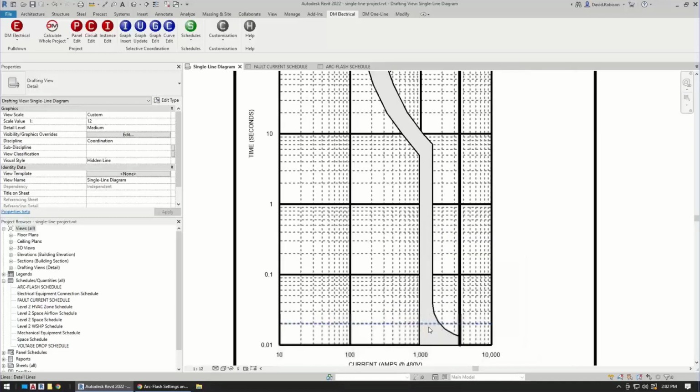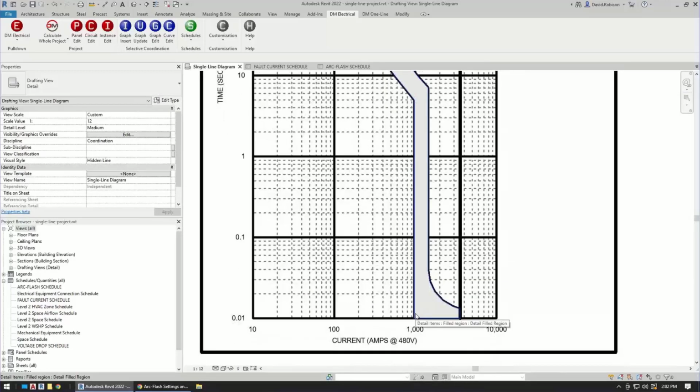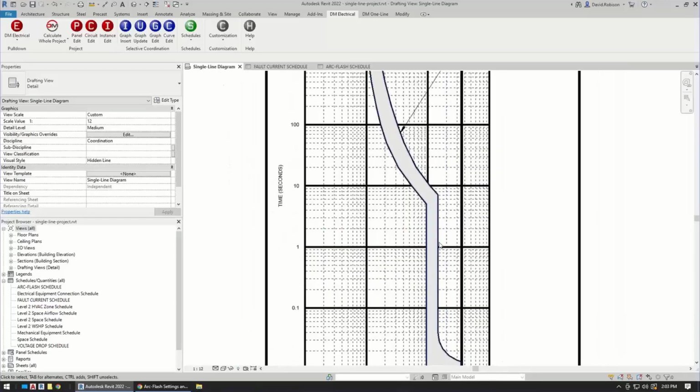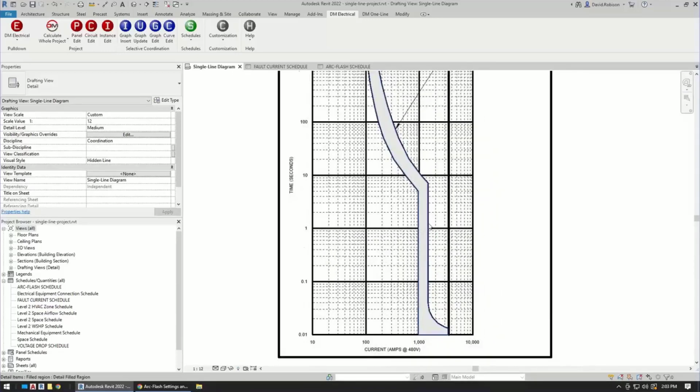So scrolling down, this is 1,000 amps. So this is probably about 2,000. So right at 1,500 amps, we go from a 2-second arc, because it's just never going to, it's going to trip in like 10 or 100 seconds, to there's a little bit of a curve here where you've got some difference, but pretty quickly it just becomes a single cycle. The breaker is going to trip in that single cycle.